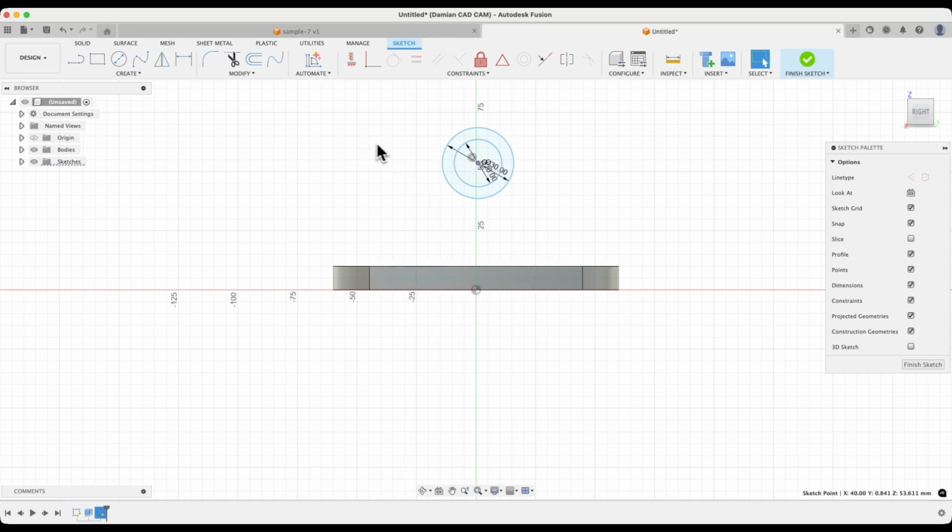Therefore, I click the left mouse button to make sure all geometries are deselected. I select the horizontal vertical constraint, select that point, and select this point. Now these points are in line. I choose Dimensioning and add the distance from this point to this point by entering 90 mm.